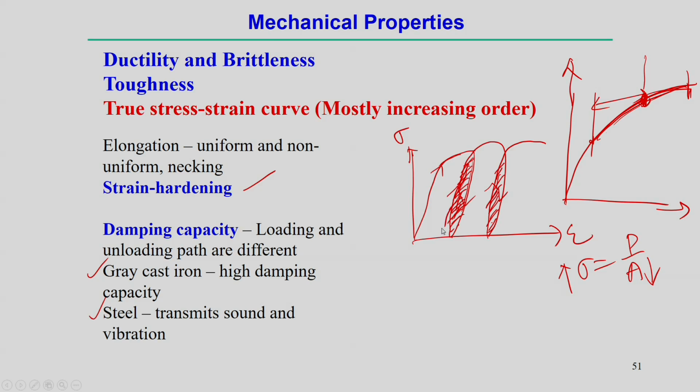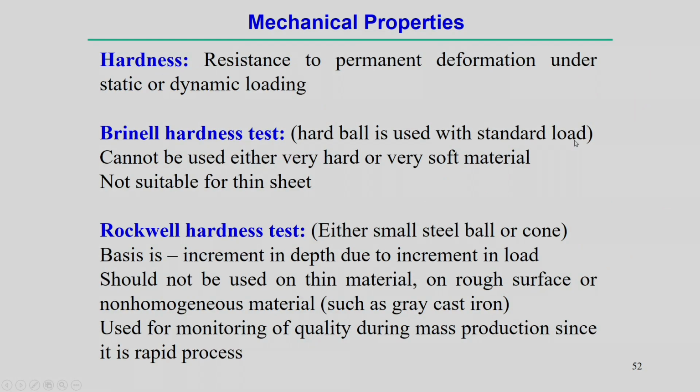That is why steel cannot absorb the vibratory kind of load, that means damping capacity is not good. So, with the loading unloading situation, it transmits sound, and of course it creates vibration, because it cannot absorb the vibration during this process. That kind of property is also important in certain applications.